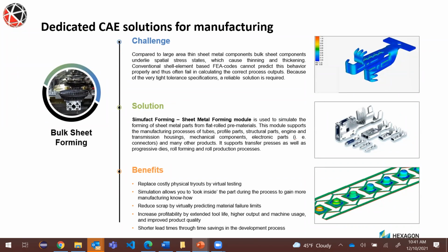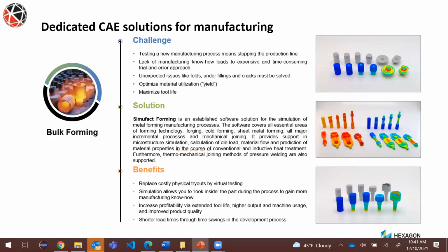In deference to Dr. Mindlin, shell theory can only get you so far. In the pure sheet stamping cases, shell theory is very adequate, but there are lots and lots of forming processes that require a three-dimensional model, right? Including things where you're roll forming and other aspects. Again, bring them up to the level of a practitioner in manufacturing to make them easy to use.